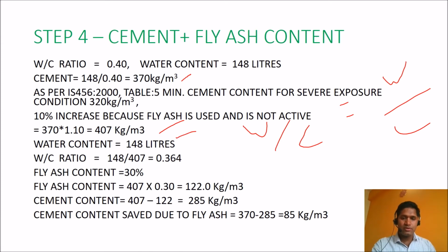Before that, we will see the revised water cement ratio. Water content is 148 and the water cement ratio is 148 divided by 407, which is 0.364, the revised water cement ratio.